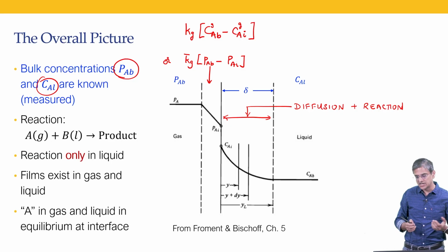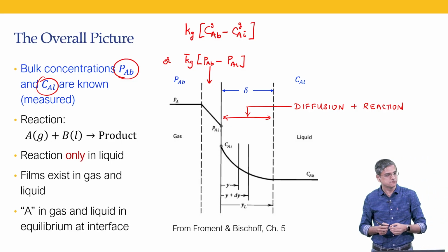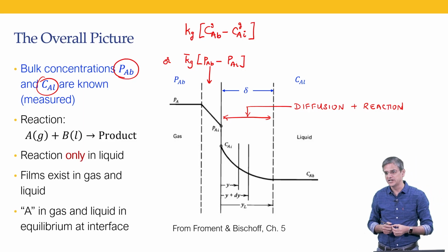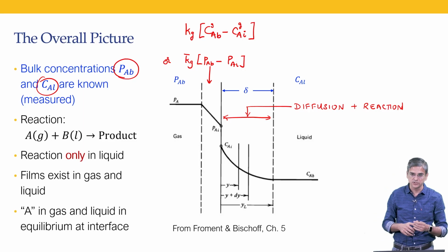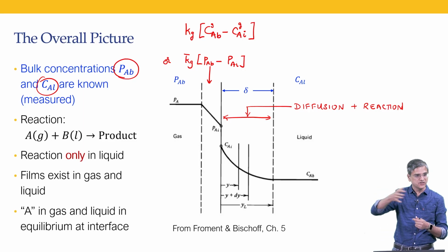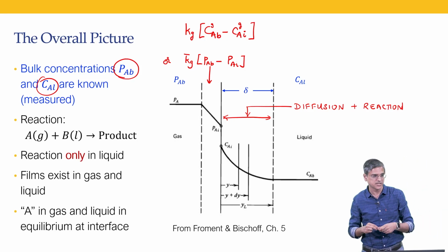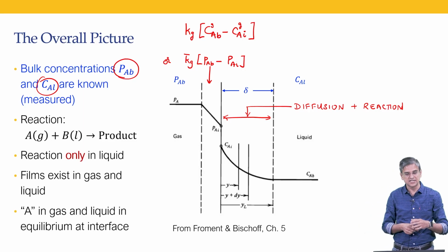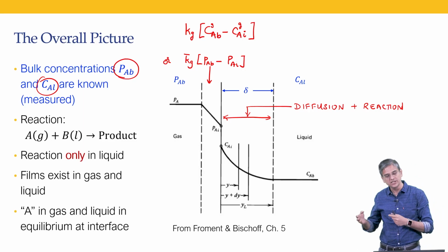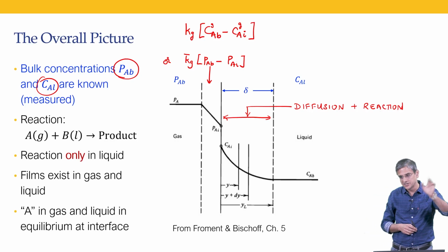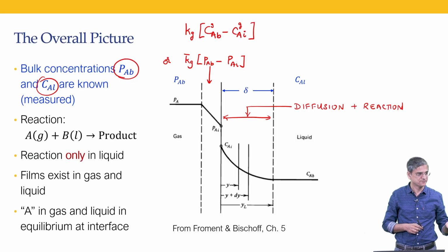For example, we have a proposal that we have put in with respect to measuring on the surface, because in the reactor it is very difficult to measure on the surface. Instead, we will take one single drop of liquid B, pass gas A on top of it, and then use some kind of an IR technique to measure the interface. And even then we are not going to be able to measure the interface only, we are going to measure an average over several thicknesses at the interface. So, those measurements are extremely difficult.